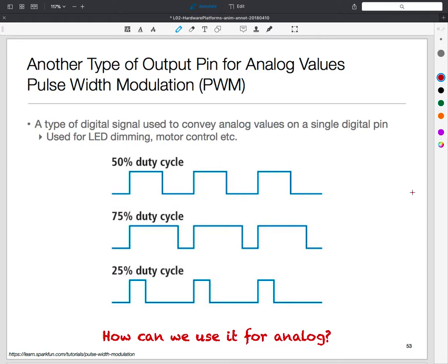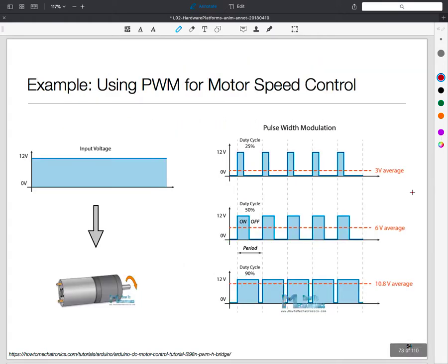And that you can do through software, right? I can decide when to make the signal go to 1 and when to make the signal go down to 0 by playing timing games within the software. I can do it very precisely using the timer hardware that already exists. So that's kind of the basic insight.